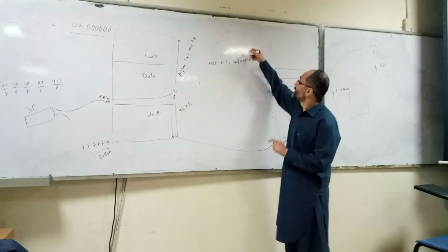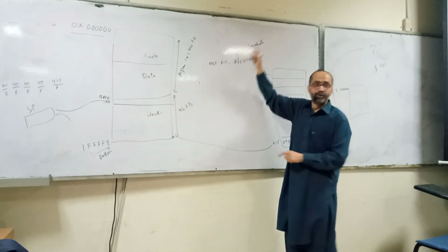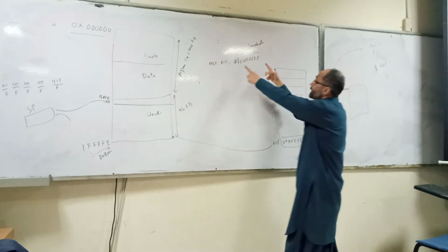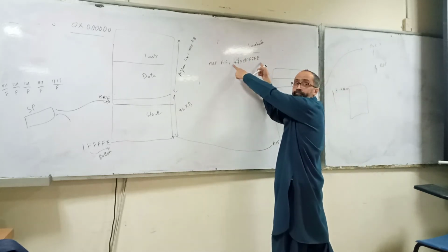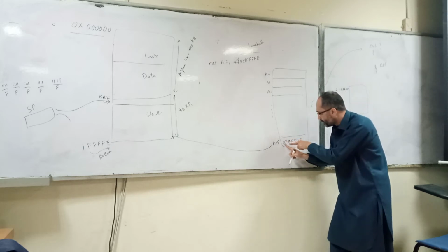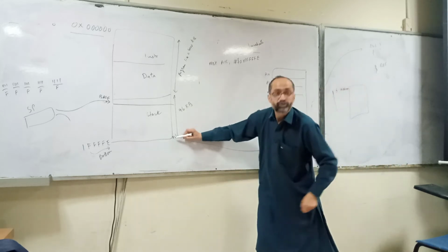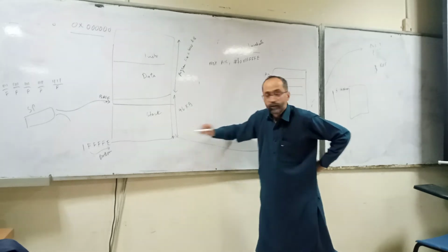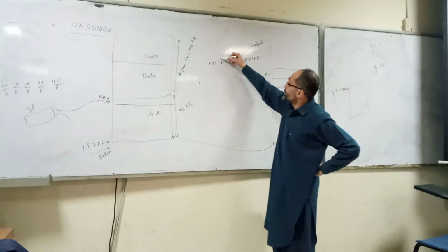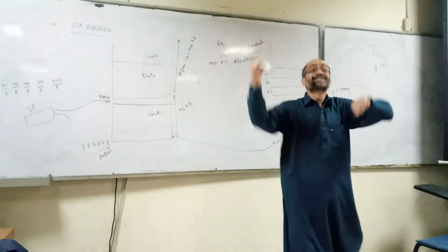Which addressing mode is this? Immediate. This one is immediate addressing mode. It means that the constant will be loaded into the address register. So now address register A15 contains 0x1FFFE, and it is pointing to this location. Which addressing mode is this? Register addressing mode, because the destination is a register.